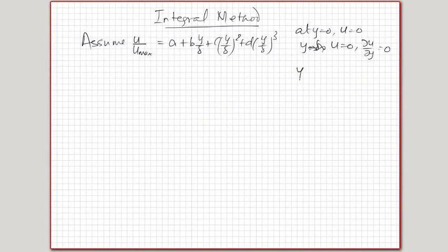And at y is equal to 0, if I take the momentum equation, which is u del u by del x plus v del u by del y is equal to g beta into T minus T infinity plus mu del squared u by del y square. In this, since u and v are 0, I'll be able to take these two out.